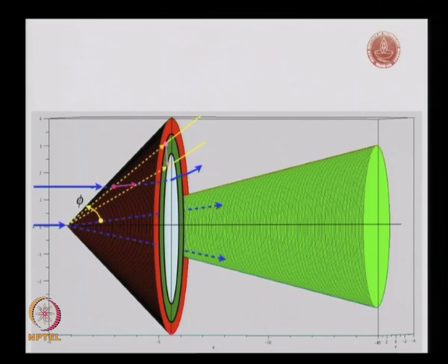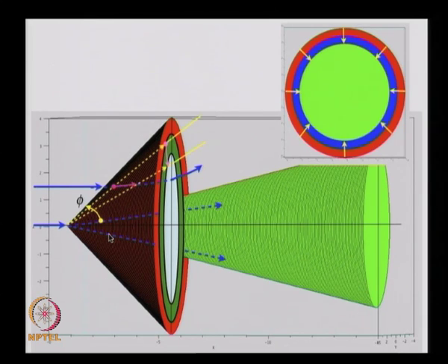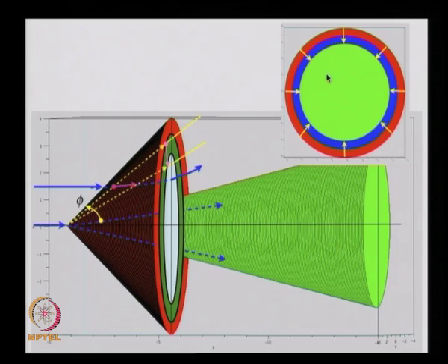It is important to see this over here. So, you move from phi, and this picture looks like this, isn't it? If I look at the planar region here, what I am doing is superposing all these flows on the cone surface onto this plane. If I keep a cone here, the flow is moving all around it. I am trying to look at it from this face, so I am superposing all that flow. So, if I were to look at this face like this, I would see the point move from here to here.